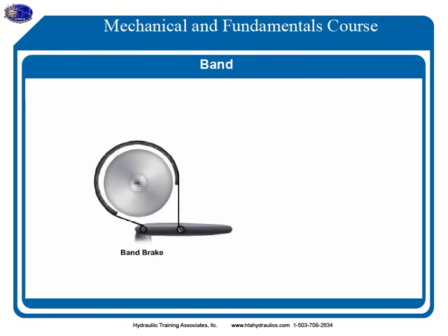The simplest, most reliable type of brake is the band brake, also called the strap brake. The brake consists of a rotating drum connected to the input and output shafts, and a flexible steel band lined with a friction material. A mechanical linkage tightens the band around the drum.